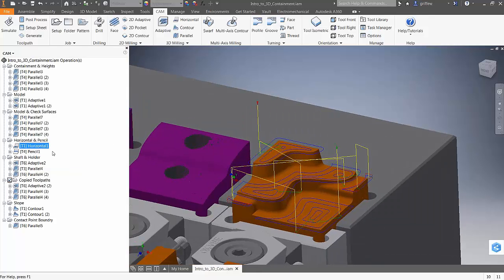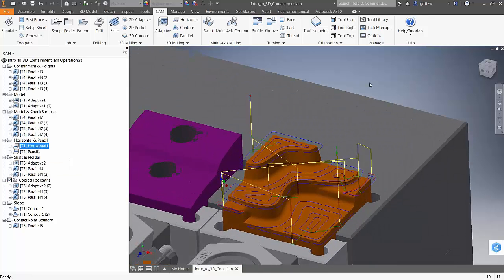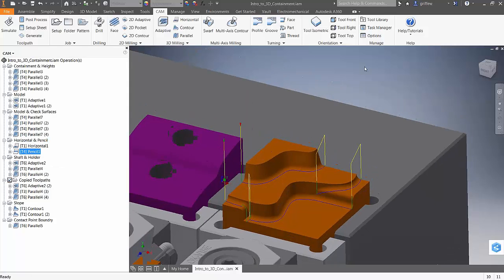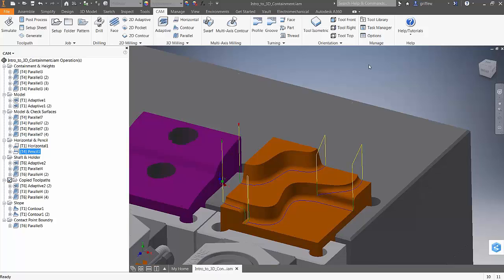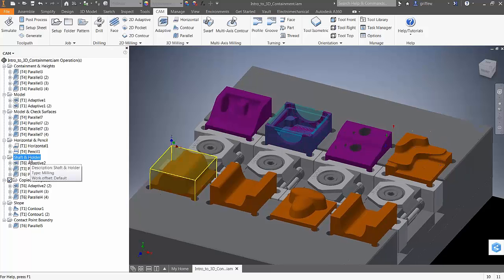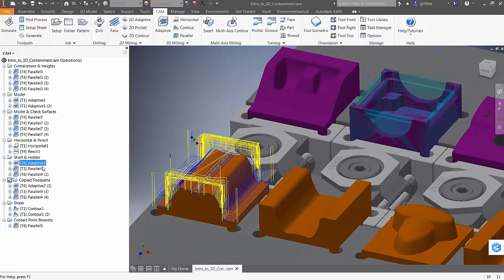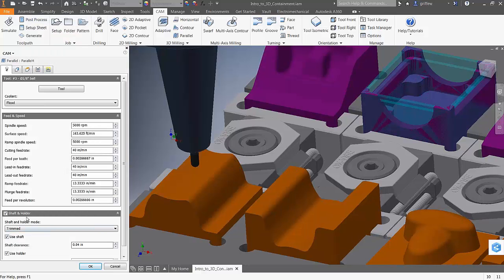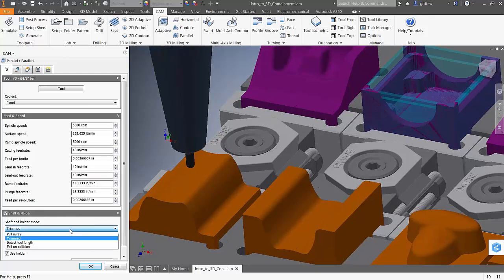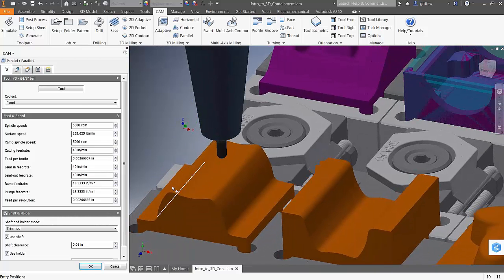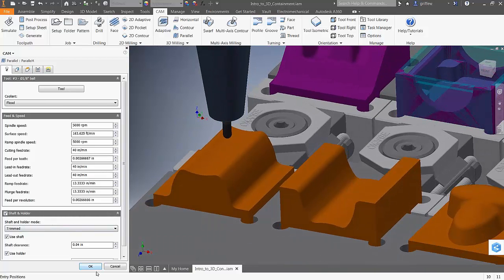So we're horizontal. These are toolpaths where they find their own containment, where it'll find all those flat areas where the tool can go most efficiently to remove that material. And pencil toolpath, again, finds its own containment area where it looks at those internal corners to apply. So in our shaft and holder, we're able to use tools like our model or our holder and shaft and holder, where we can trim. We have other ways, pull away. We have other strategies where we can keep that tool or the tool holder from gouging our part. Another way to contain the toolpath.